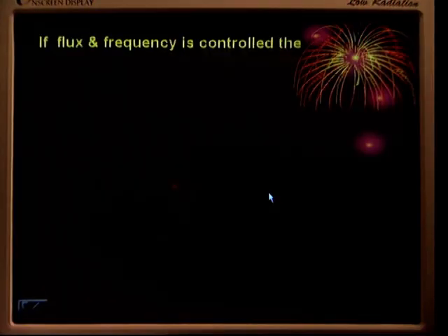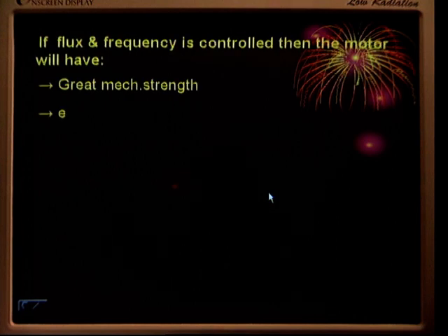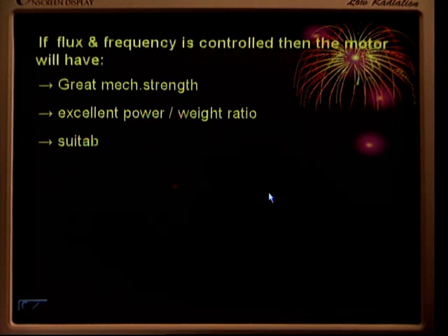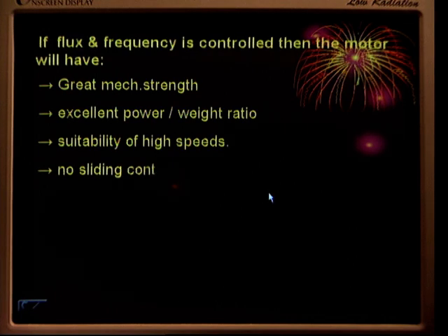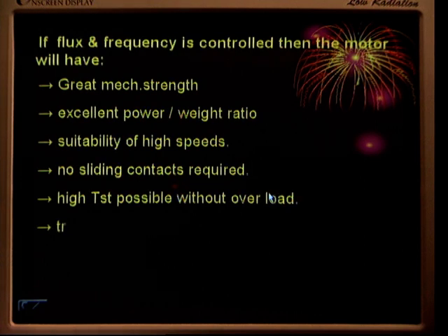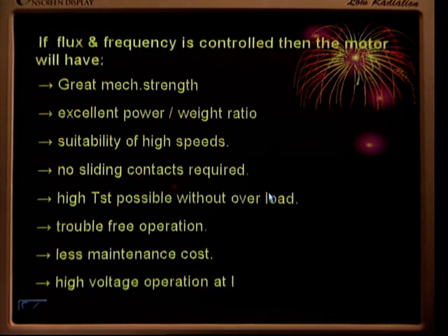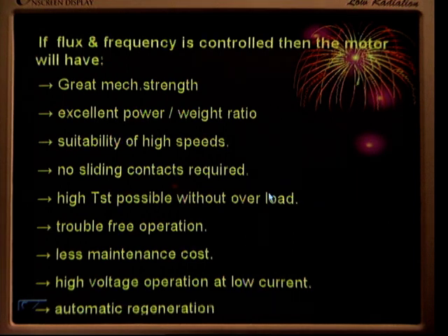If flux and frequency are controlled, then the motor will be excellent for traction, and it has different merits: great mechanical strength, excellent power-to-weight ratio, suitability for high speeds, no sliding contacts required, high starting torque possible without overload, trouble-free operation, less maintenance cost, high voltage operation at low current, and automatic regeneration is possible.